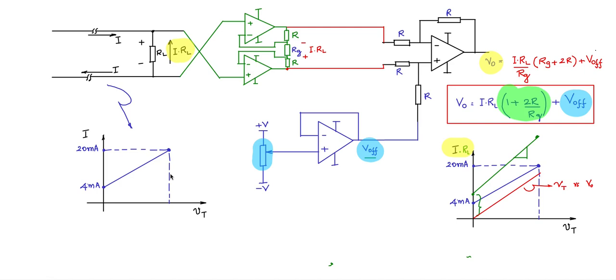And then the output of that should go through an anti-alias filter so that you band limit the signals. After band limiting the signals, you pass it to the input of the ADC and sample it such that the sampling frequency is greater than twice the band limit.